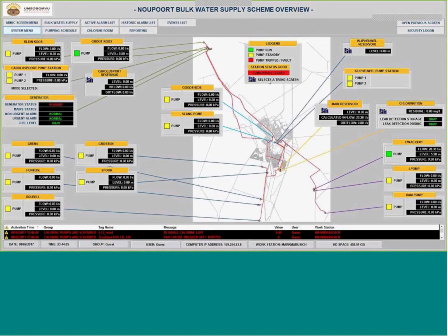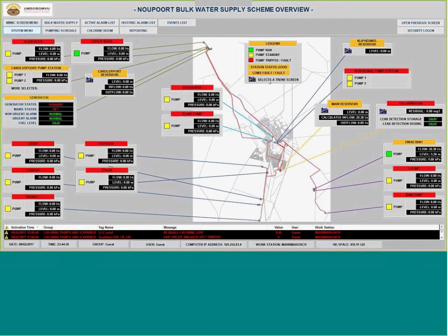I don't know where I learned this, but as I teach different training classes, I found out that about 10% of men are colorblind, a little bit less than women, about 0.1% of women are colorblind. So there's a chance that 10% of your operators can't even see the status changes on the screen. So it's highly recommended to not only make changes with the color, but maybe words and maybe even symbols, to go from a circle to a triangle or to a square, denoting when you have changes there. So that's good. I'm glad you guys figured this out on your own.